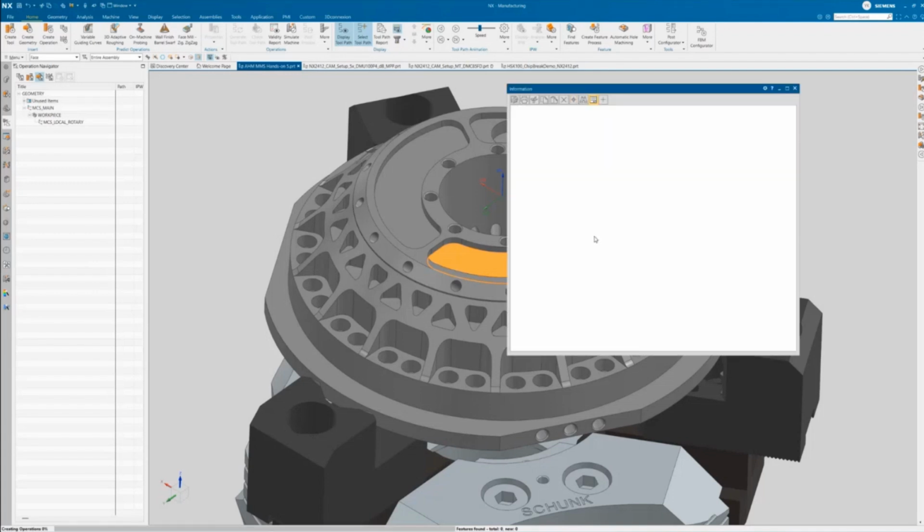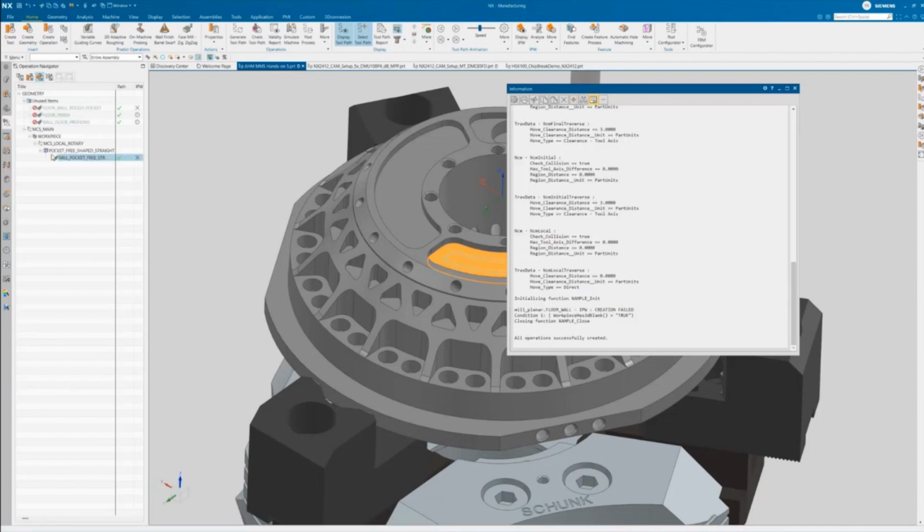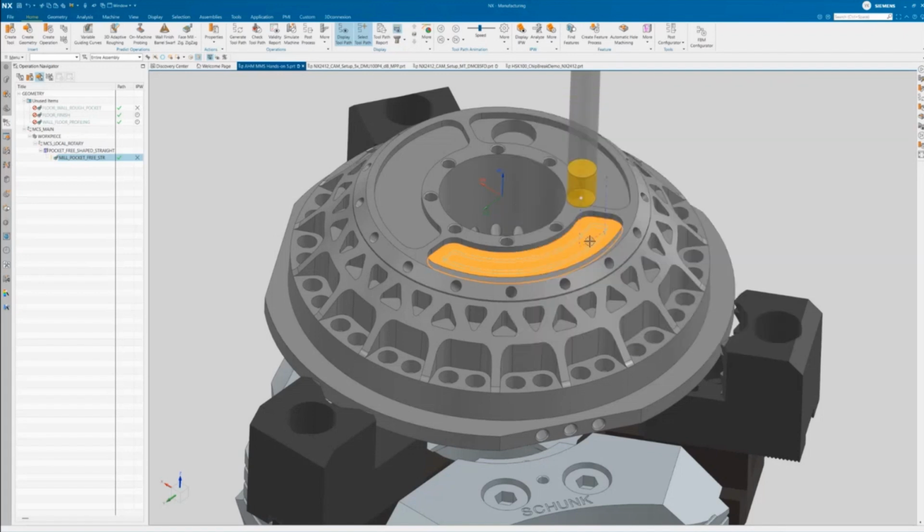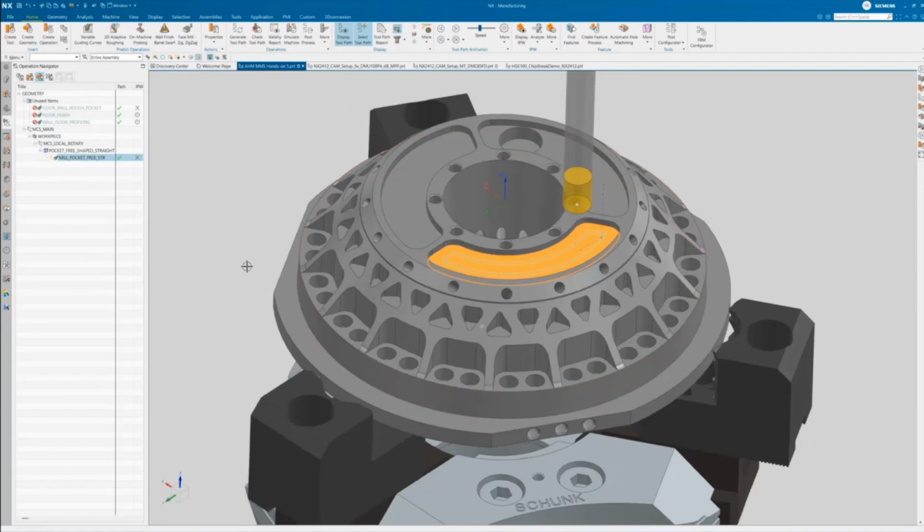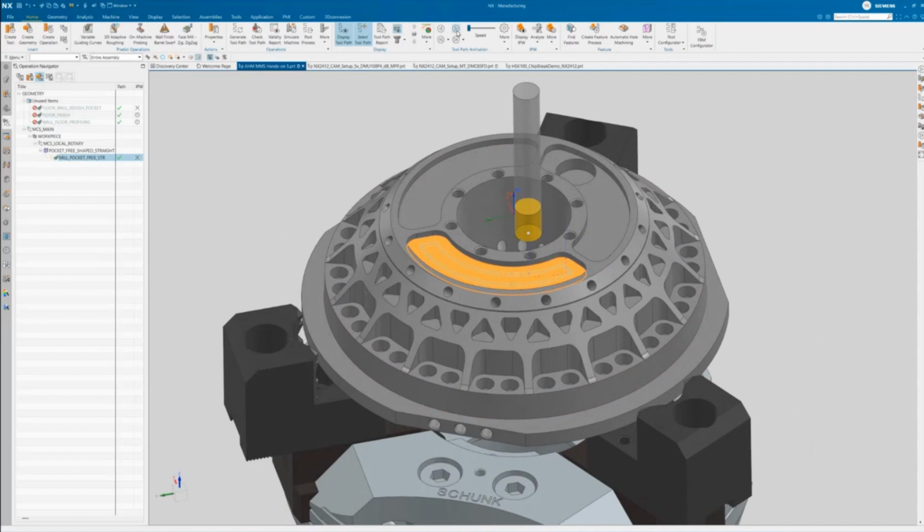If you go ahead and click on that, NX is going to calculate and create a toolpath. It's going to take the tool, and basically follows the same procedure that feature based machining usually does, but in this option we don't have to go to our machining feature navigator, select the features and create the feature process, so we can skip that. That is the advantage of the make machining suggestion. As you can see here, it has created a toolpath based on the face that I've selected. These are basically out-of-the-box solutions which come with the NX installation.